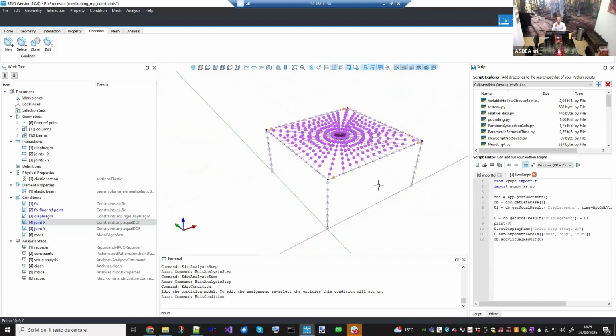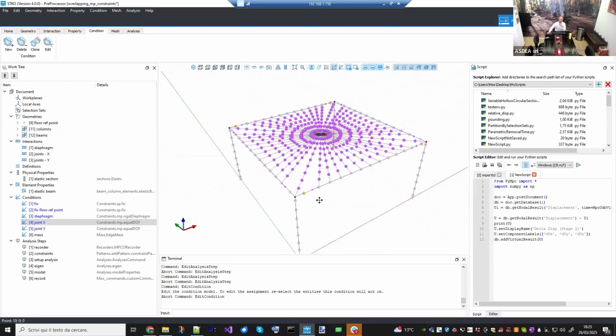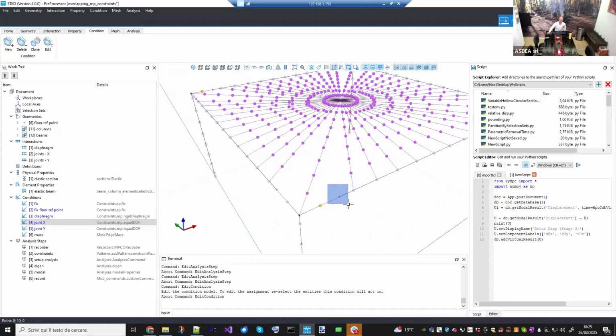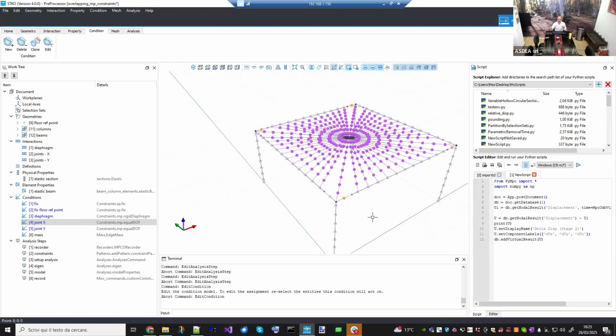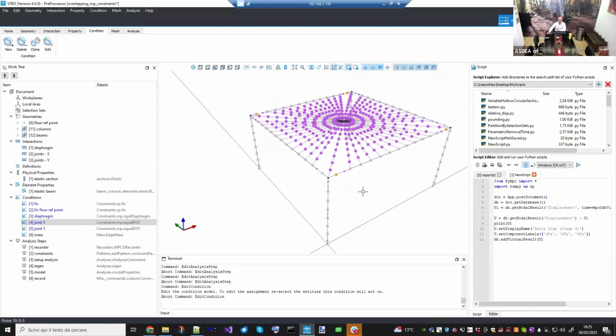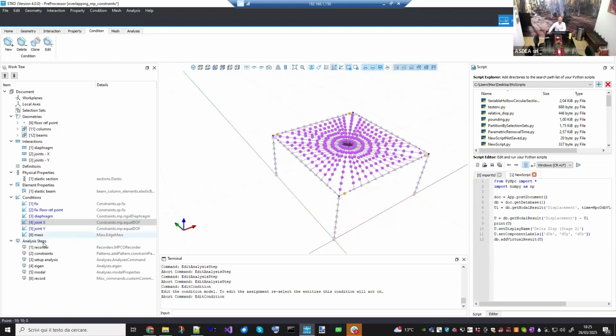This is very typical, but this usually leads to issues in OpenSees if you use the transformation handler, because the transformation handler is not able to apply this kind of overlapping multi-point constraints. And well, of course, there is also another issue for this node here, because this node is slave in one equation, but is also slave in another equation. So the transformation handler is not able to handle this overlapping kind of constraint.